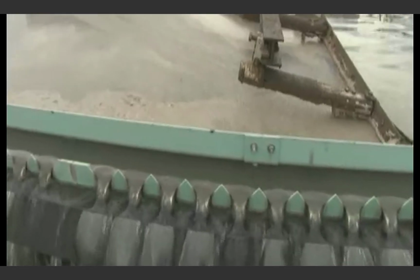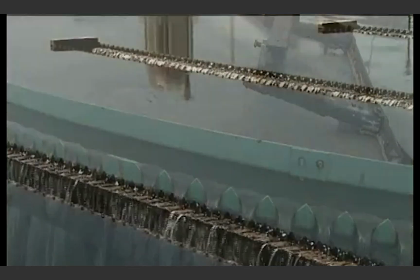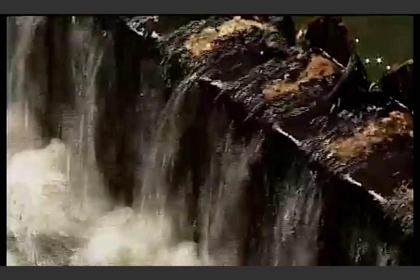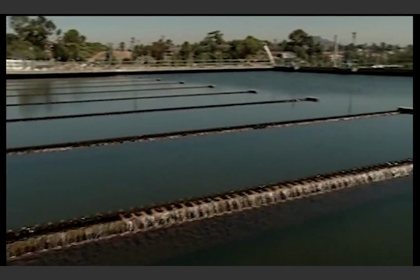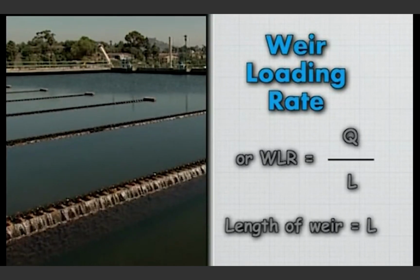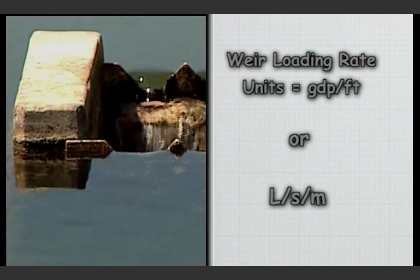The weir overflow or loading rate is a lot like the surface overflow rate, except instead of looking at the basin as a whole, we are interested only in determining how fast the water is flowing over the weir. This is important in identifying high velocities near the weir, which adversely affects the quality of the effluent. The weir loading rate, or WLR, is equal to Q, the flow, divided by L, the length of the weir. Weir loading rate units are typically gallons per day per foot or liters per second per meter of weir.